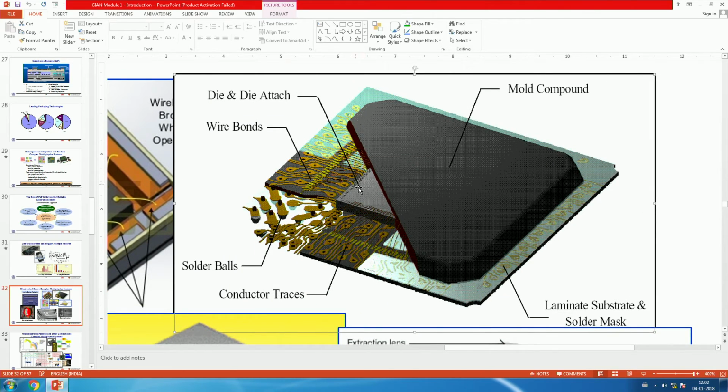But this chip has to be connected. All the ICs and the electronics on that chip have to be connected to the substrate so that they can be connected to the next component, the circuit card. And if you look very carefully, and maybe you can see it in your handout, there are wire bonds coming out from that chip and getting connected to these bond pads here. So the bond pads on the chip, bond pads on the substrate, and there are thin, slender wire bonds connecting them. And then you can connect to these bond pads from the other side, from the underside of the laminate, and now you can have electrical signals going in and out of the chip.